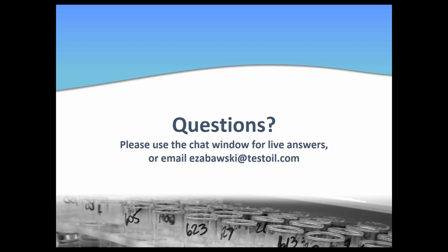Next question, again from Warren. Is it useful to do direct reading ferrography? Well, understand direct reading ferrography is not a whole lot different than ferrous wear concentration. It's a similar magnetometer-based test. The only difference is it classifies large versus small, which is a rough estimation anyways. So it's a good screening tool. It's a good trending tool. It's a quick pass without getting into something complicated like analytical ferrography.